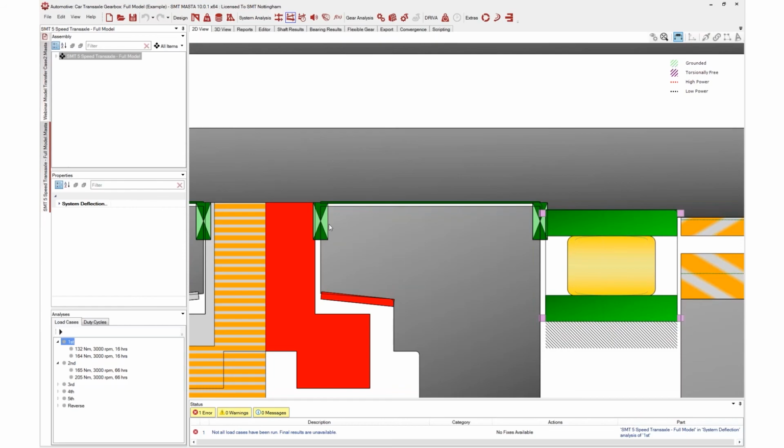If the bearing moves in the opposite direction, it will have no stiffness at all. So if they both have 50 microns of clearance, then the total will be the sum of the two.